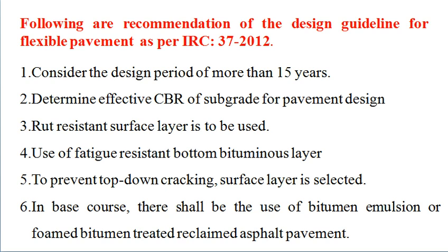rut resistant surface layer to be introduced. Now rut resistance, or rutting, is a permanent deformation of the pavement, and it is basically caused by the repetitive application of traffic loading. So a layer was to be introduced which shall resist this deformation of the pavement under the influence of the repetitive loading of the vehicular movement onto the pavement.